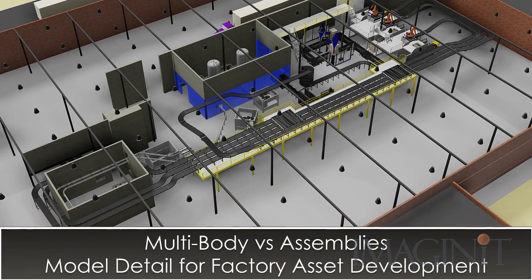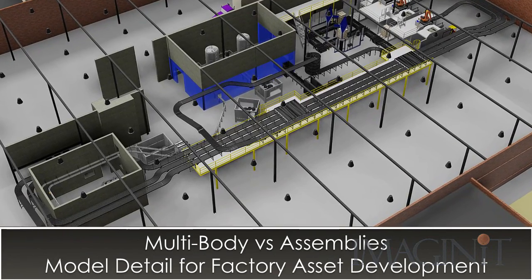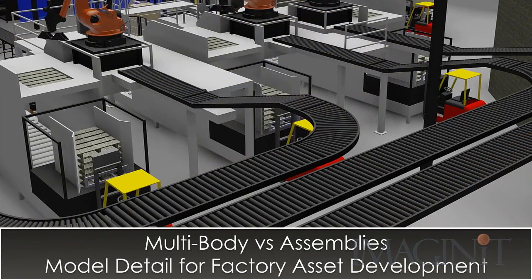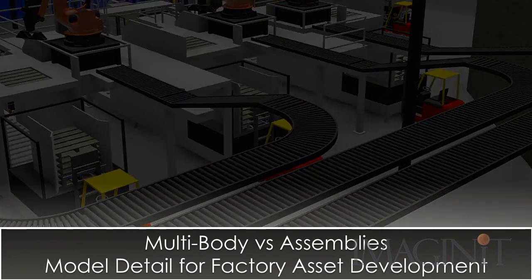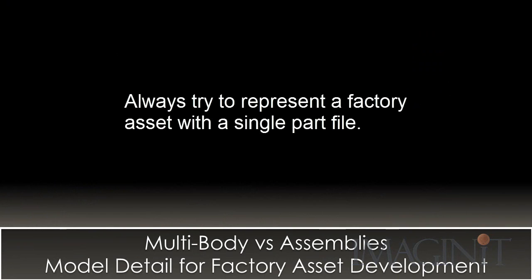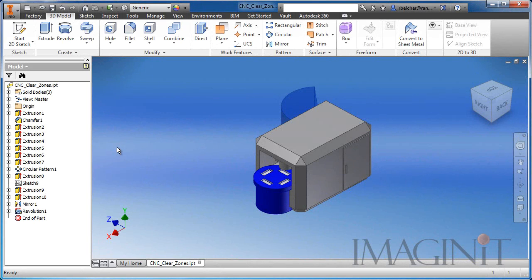It's important to remember that the factory layout process often requires the placement of hundreds or thousands of assets. That's why it's necessary to publish assets with the simplest model detail possible. But it's also important that we create our layouts using the fewest files possible. This is why we should always try to represent our assets using a single file instead of an assembly. Inventor has a fantastic workflow that allows us to simulate an assembly using a single part file. The workflow is called multi-body modeling.